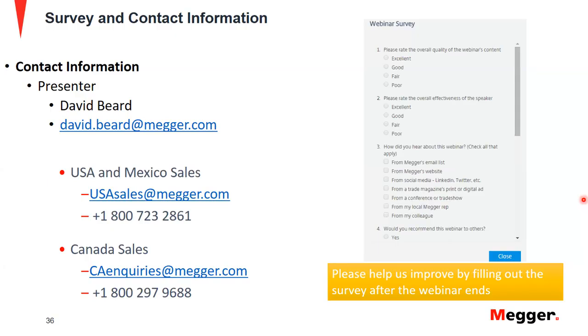All right. So Sughosh, does the RTMS software allow for different frequencies, such as an aircraft, which would need 400 hertz? Absolutely. On the RTMS software, we have the option to change these frequencies independently for different channels of currents and voltages. Another nicer feature on this software is that you can generate frequencies of different levels on the same channels. One channel can generate up to 4 waveforms of different frequencies. I hope I answered the question.